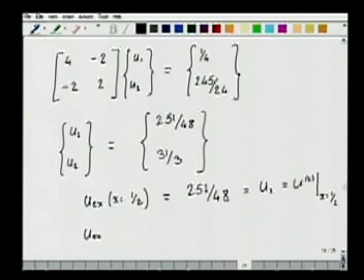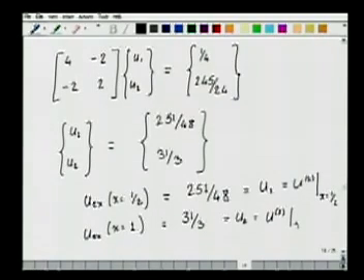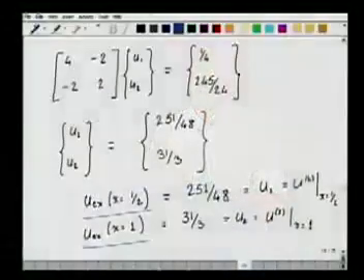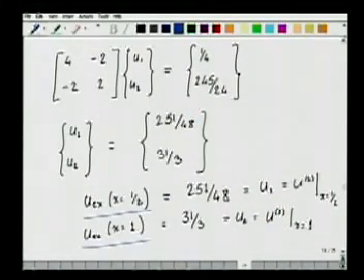Similarly, u exact at the point x equal to 1 will be equal to 31 by 3, which is equal to u2, which is equal to the two-term solution evaluated at x equal to 1. So you see that the exact solution matches the two-term solution that we have taken using these special phi's that we have defined at the points x equal to half and x equal to 1, which we have called as also points x1 and x2.